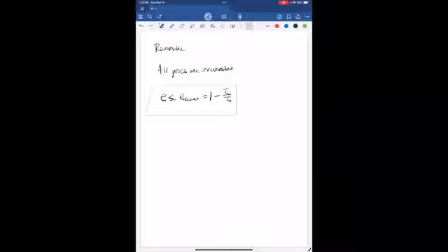For heat pumps, this translates into the coefficient of performance in cooling mode is less than or equal to Tc divided by Th minus Tc, and the coefficient of performance in heating mode is less than or equal to Th divided by Th minus Tc. So that also puts limits on heat pumps, and these maxes come because a Carnot heat engine, since it's reversible, you can reverse its process, and in reverse, it's a heat pump.